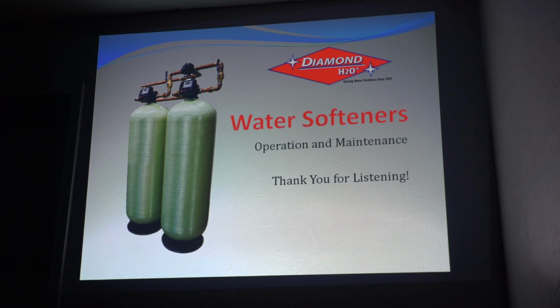Yes, I do have one. You mentioned that you put gravel down in the bottom of a softener, correct? Yes. Isn't gravel mostly made of calcium? We use a quartz. Okay. Good question. It's a washed quartz. Okay. So there's nothing, no sloughing off of any.